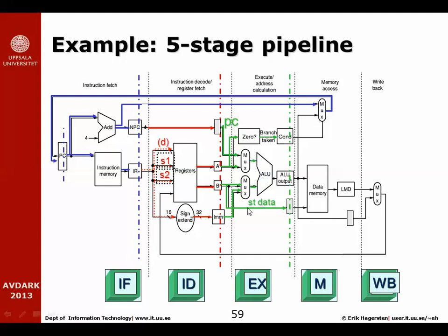So here we have lots of different ways of putting the ALU into business. We have 2 muxes here. The top mux can either choose to read in the PC value that comes from this latch over here, or one of the source register values, and put that as one of the inputs to the ALU. The lower mux can choose to either put the second source register value into the ALU, or put this intermediate constant into this ALU. And exactly the choice these 2 muxes will make really depends on what instruction we're executing.